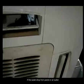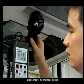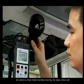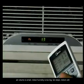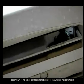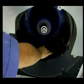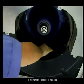Step 2. If water drops from the panel or air outlet, please check if the air outlet is blocked. Air volume is small, indoor humidity is too big, the fan stops, the indoor unit doesn't run, or the water leakage is from an indoor unit which is not powered on. If a problem exists, please repair it one by one. If it is normal, please go to the next step.